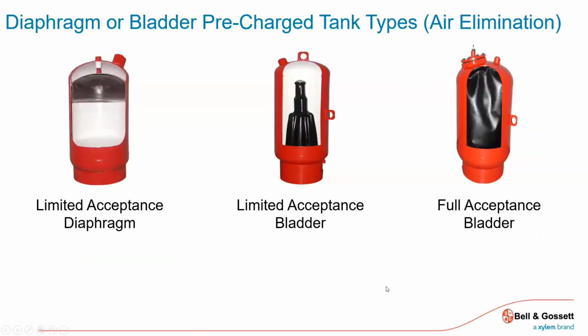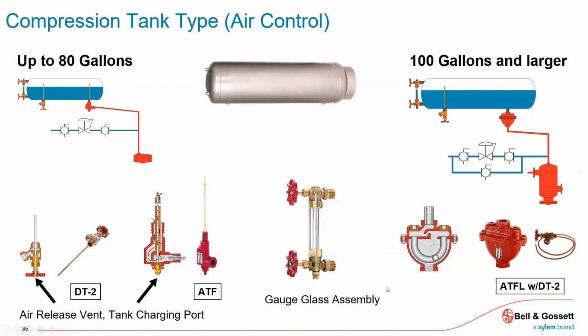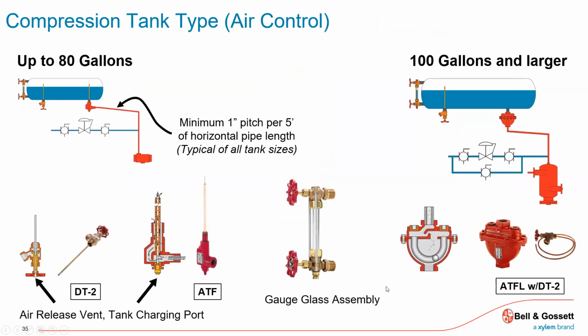And the other thing about the tanks is they can be smaller. For the same system, when you did an older style tank, you're already starting with 55% of that tank's volume filled with water. When you go to this style tank, any one of these style tanks, there's no system water in that tank when it's cold. It's only when it gets hot.